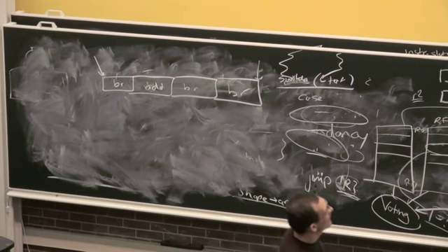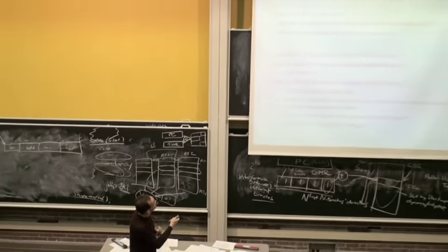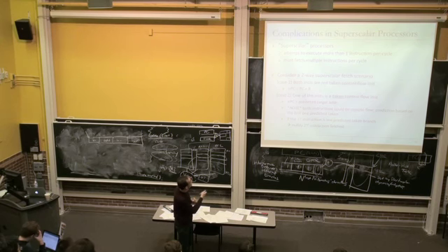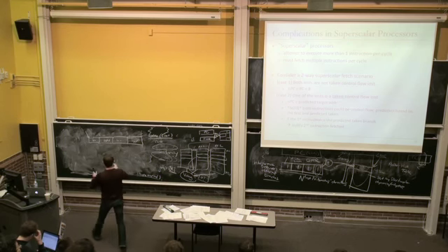Here I sketch out basically a two-way superscalar processor. If both instructions are not-taken control flow, then it's easy. Your next PC is PC plus 8. If one of the instructions is taken control flow, then you need to predict the target address for one of those instructions. The question is, how do you predict the target address?